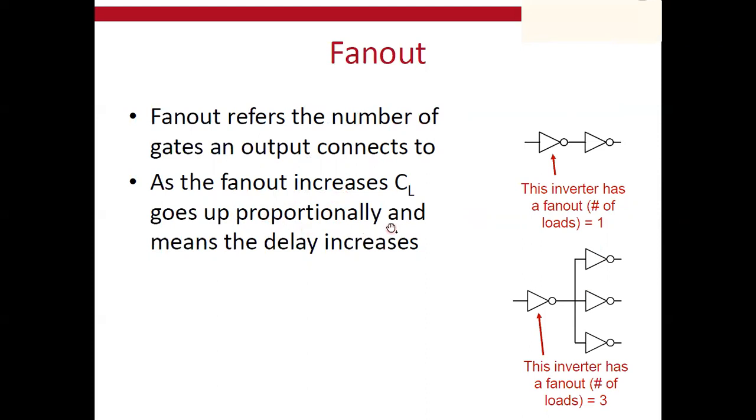This is very important because, as I just mentioned, the input capacitance of your gate is a load capacitance for the previous gate. For example, in the figure above, your output capacitance is mainly driven by the input capacitance of the next gate, which is this one. Here you have three logic gates in parallel.